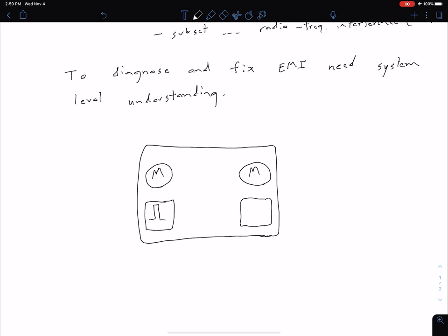So this motor is also going to have a circuit, which is outputting some pulse. Let's say maybe one motor is outputting more pulses in the same amount of time. What they would want to do then is increase the speed of the left motor such that both motors are going at the same speed and the robot moves in a straight line.